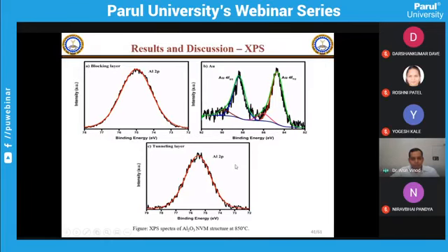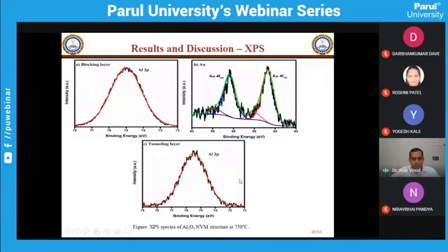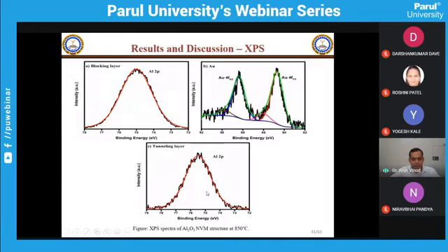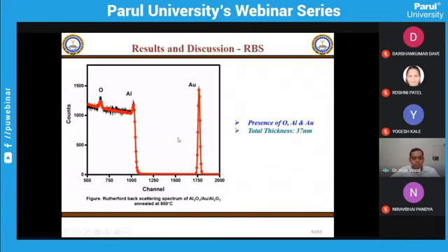In this case, which is very interesting, in the tunneling layers, which we can see as deposited, at 750, and at 850, there is no formation of intermediate oxides like SiO and also hafnium suboxides. There is no formation of suboxides in this case.